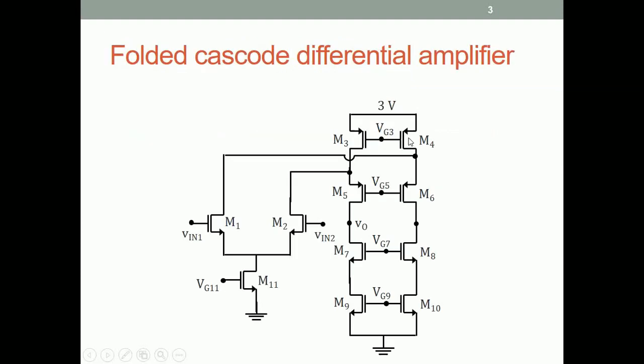M3, M4, the current in M3 is equal to the sum of the currents in M2 and M5. Therefore, M3 carries about, well, if these currents are equal, then twice the current of M2 or M5, and therefore M3 and M4 are larger transistors than the rest of the transistors. Qualitatively, right? These currents are not necessarily always equal, but M3, M4 are certainly larger than M5 and M2.